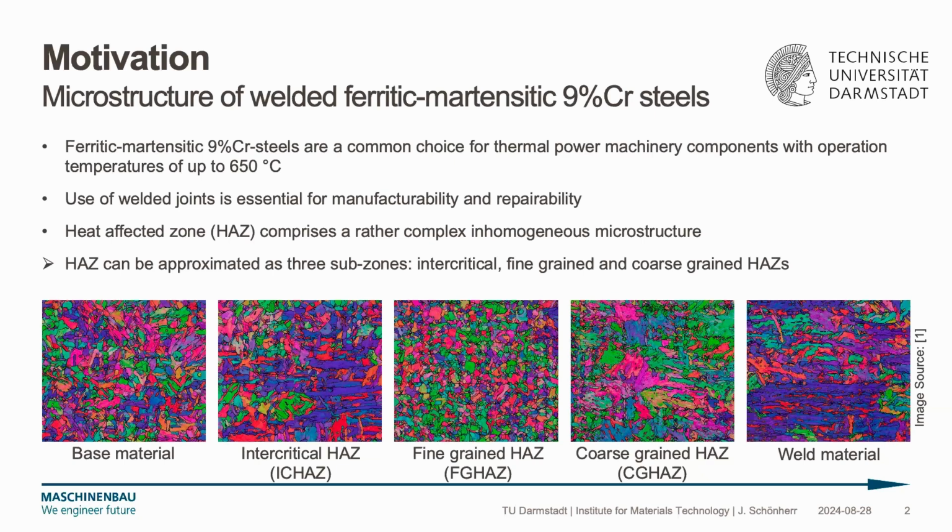And if you have huge components like turbine housings of gas turbines, these welds often have to be made in place, and therefore no heat treatment of the whole component is possible. So there's only a small available area for heat treatment, and it should also be repairable. And therefore, if we are welding, we cannot obtain a homogeneous microstructure in the weld.